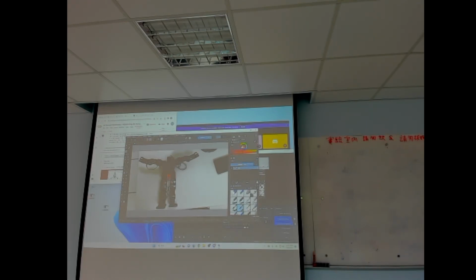So the question then is, the robot moves forward? If the robot walks, I think it makes sense to have the coordinate system aligned so that one of the axes is pointing in the direction that the robot would walk when it walks forward. It doesn't make sense to have the coordinate system aligned this way or this way. So Z goes up, then X seems a reasonable choice: if the robot moves forward, then it moves along the X-axis, which then means that the Y-axis is pointing to the left.